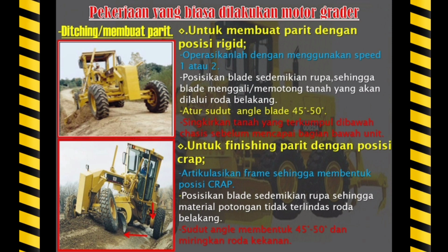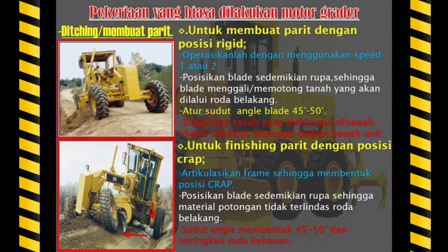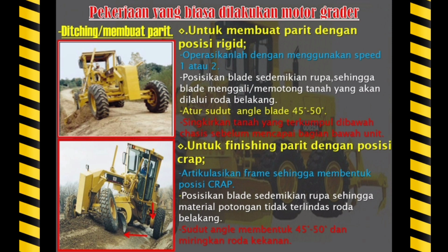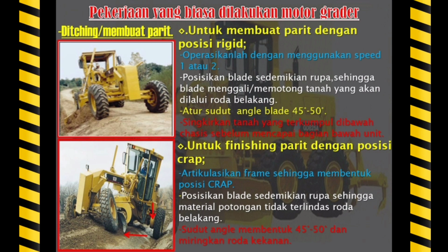For finishing the trench with the craft position, articulate the frame so that it forms the craft position. Position the blade so that the cut material does not run over the rear wheel. The angle forms 45 degrees to 50 degrees and tilts the wheel to the right.